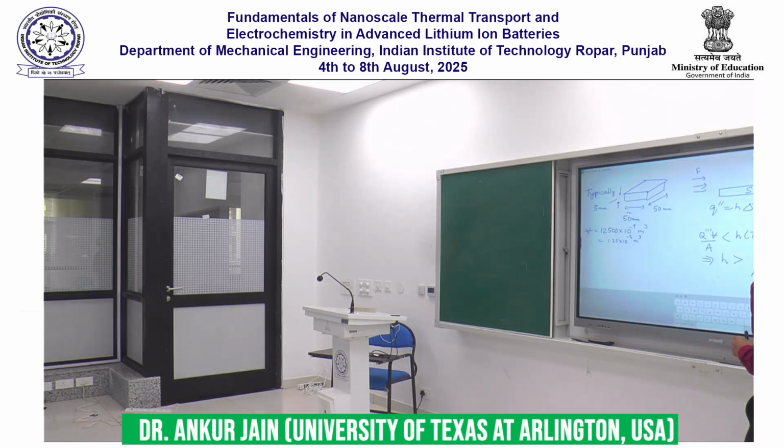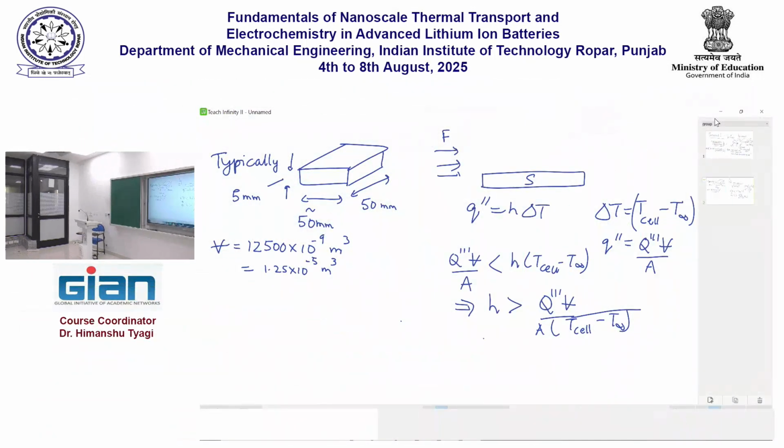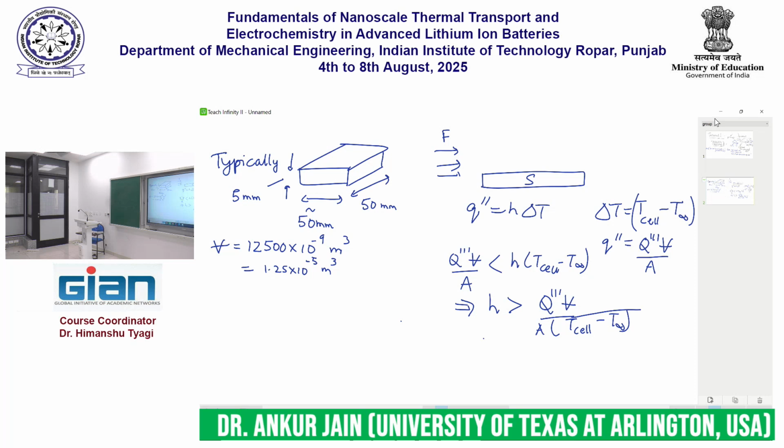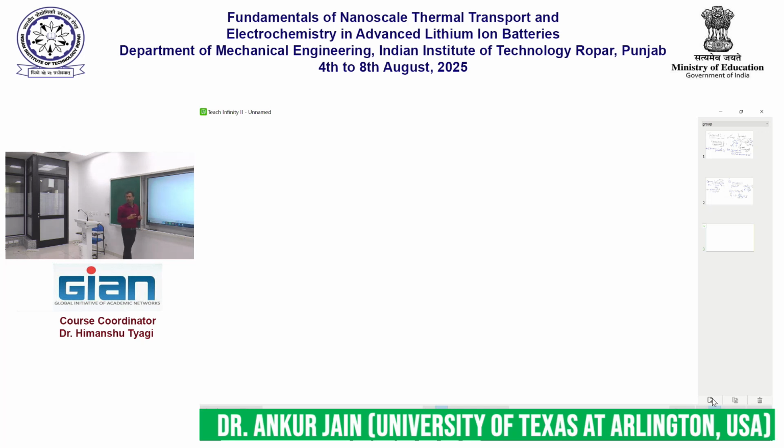Let's go back here and I want to make a few more comments. The story in a cylindrical cell is even more interesting, because in a cylindrical cell, if I blow air over this cell, then this cell is going to get cooled very nicely on the outer surface, but deep inside the cell will have very poor cooling.